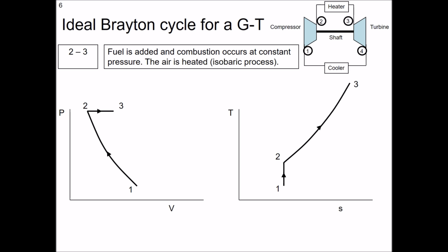So what we see is a substantial increase in temperature. That makes sense. We're burning jet fuel in air. Okay. And we see a huge increase in entropy because we're taking some fuel, which was nicely ordered. Its energy quality was very good, and we're degrading that energy quality by burning the fuel.